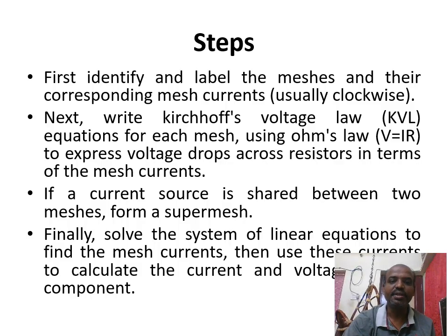The first step: for a given circuit, we need to identify the number of closed paths there. After identifying that closed path, we need to name that closed path and also assume the current flow direction in clockwise.